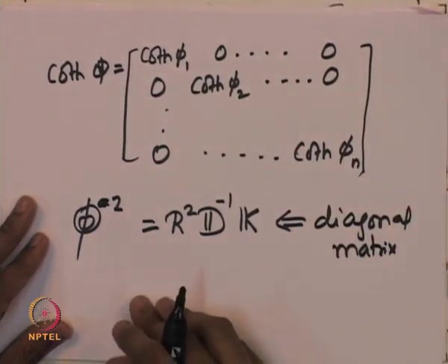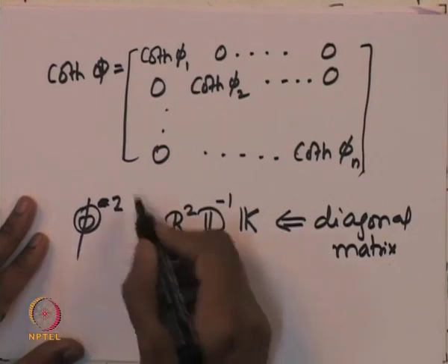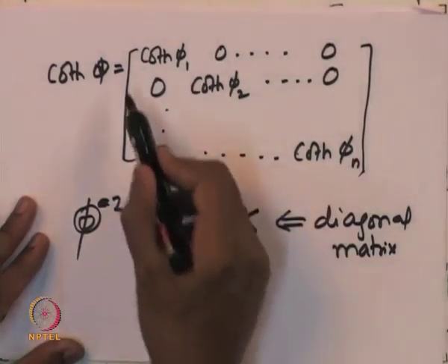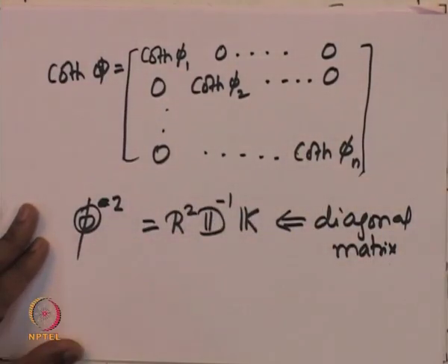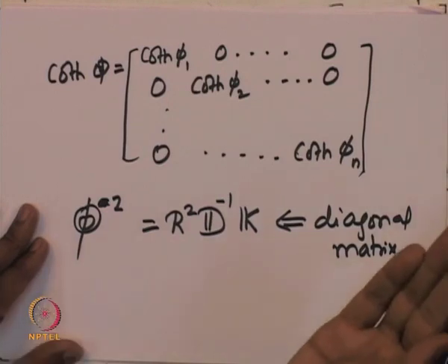Once we know the Thiele modulus matrix, we should be able to find out the coth, and we can substitute that in the expression for the relationship between the Thiele modulus matrix and the effectiveness factor matrix. From that, the effectiveness factor matrix can be found, and using that one can find out the actual observed kinetics and express it in terms of the true kinetics. So, from experiments, if we measure the actual kinetics and know the effectiveness factor, we can use that expression to find out the true kinetics of the network of first order reactions.